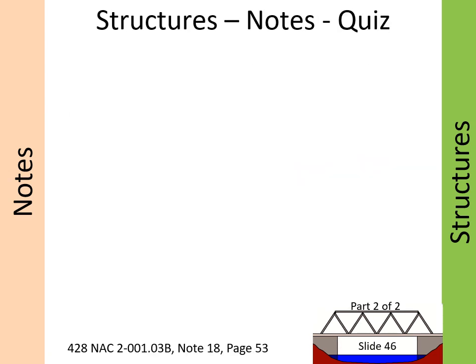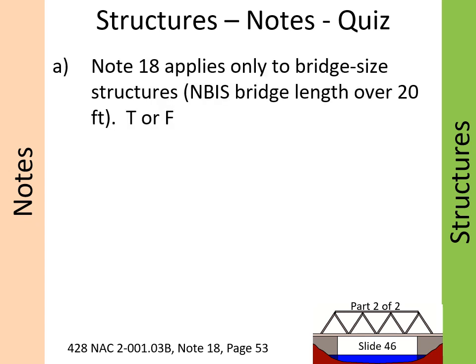Now for some quiz questions on the notes. Question A. Note 18 applies only to bridge-sized structures, length over 20 feet. True or false? The answer is false. Note 18 applies to structures 4 feet and longer, to non-buried structures and bridges.